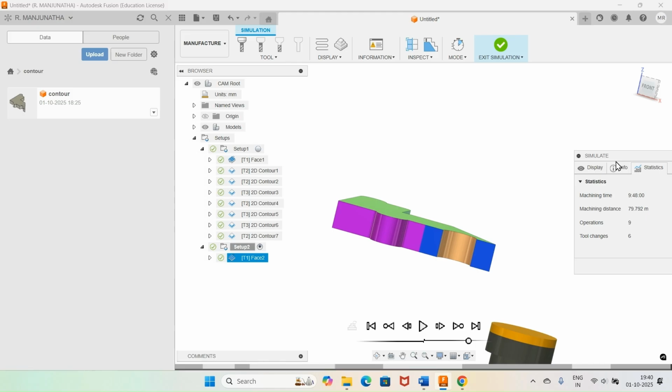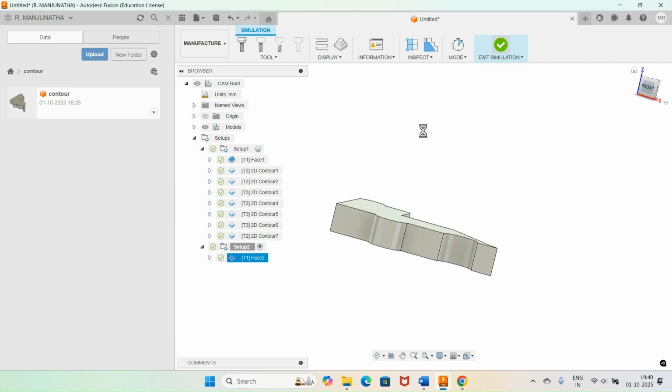And you can also reduce the cycle time by considering different ways of doing things, but the only control is on the feed rate and the cutting speed. Again, I'm telling you, I'm stressing on this. Once you are considering the cutter, we need to look at the catalog of the cutter, whatever you are using, and you can also edit the cutter dimensions. We will consider all those things in our future videos. Now once you do that, I will just exit the simulation.